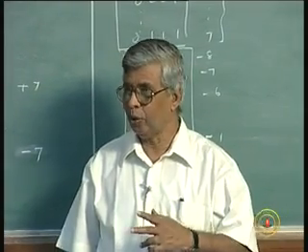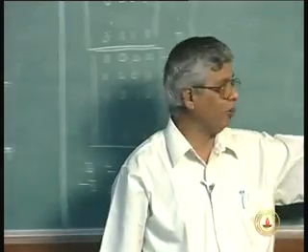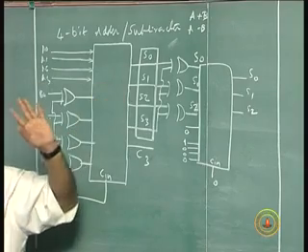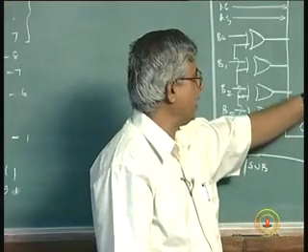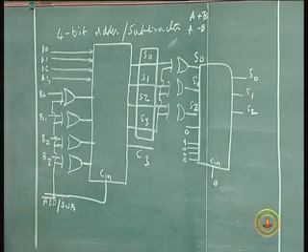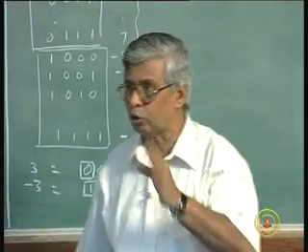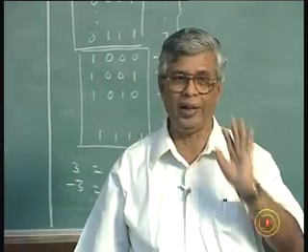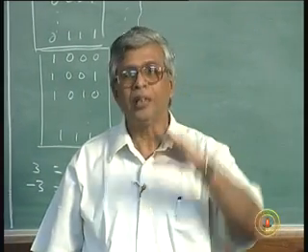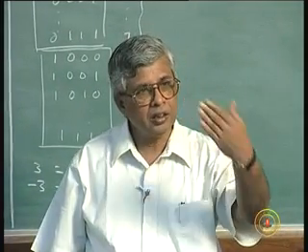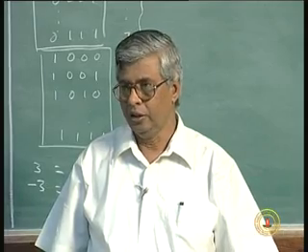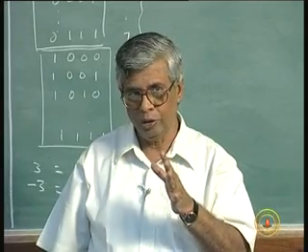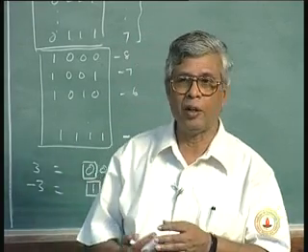This will be the magnitude of a negative number. If you had a negative number as the output, there are 2 ways of representing it. Either you can represent it as it is, S3, S2, S1, S0 will give you the negative number in 2's complement form. You can keep it as it is, store it as it is, use it as it is in the next stage of addition or subtraction. That is what computers do.